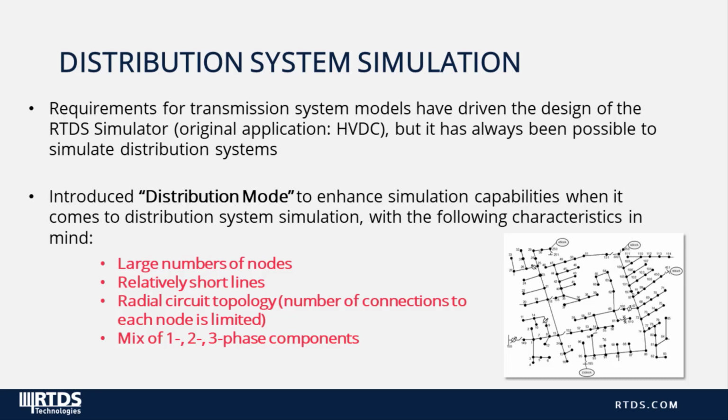So for a long time, it's been theoretically possible to do something like recloser control testing with the RTDS simulator. However, as we saw more and more customers with a big focus on distribution simulation, we made some changes to the simulator capabilities based on some common characteristics of the distribution networks that customers were simulating. So typically, these systems have a larger number of nodes in one tightly coupled area with relatively short transmission lines. So no lines long enough to mathematically decouple the system into subsystems.